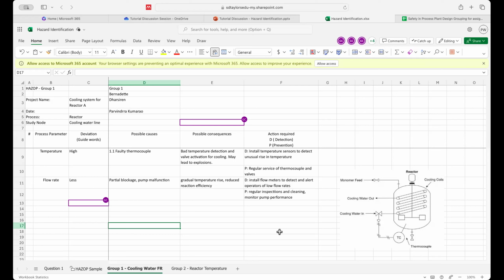We only want a few alarm systems so that when the alarm rings, the operator takes action. When you have too many of them, the first thing you're going to hear is a symphony in your process line, because it will ring all the time with all the different pitches. Second, when you have too many alarms, people become immune to the alarm and won't take action on it. So when we do HAZOP, we put in all the alarms that are needed, but in real practice we have to identify which ones are critical. We only install those, so when it rings, the operator must take action.